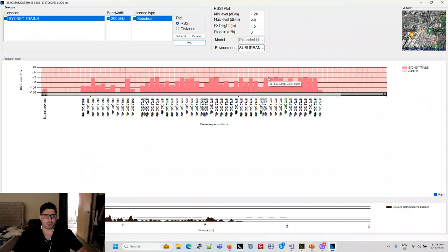So you can see, guys, when you hover the mouse here, you can see the signal level and the center frequency as well, depending where you position your cursor. So you can see negative 75 roughly dBm at this stage here, and this one has a weak signal. You're looking at negative 117 dBm, and you see here this is empty because obviously there's no label. So this is really a nice way to understand what the spectrum would look like if you have a scanner there, or if you want to really identify reusable frequencies.